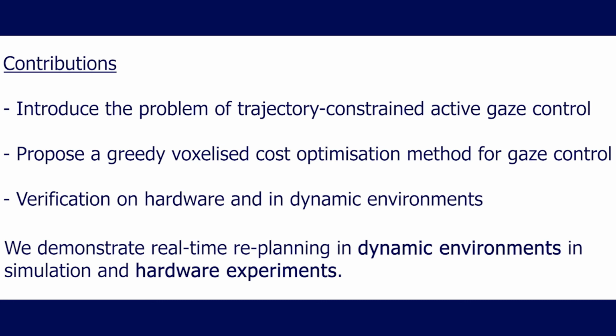To conclude, this work introduced the problem of trajectory-constrained active gaze control and optimizing sensor poses over the course of a trajectory for providing effective collision avoidance. We have proposed a novel solution using a greedy optimization approach with voxelized rewards and motion primitives, and we have demonstrated its effectiveness in 2D and 3D environments.